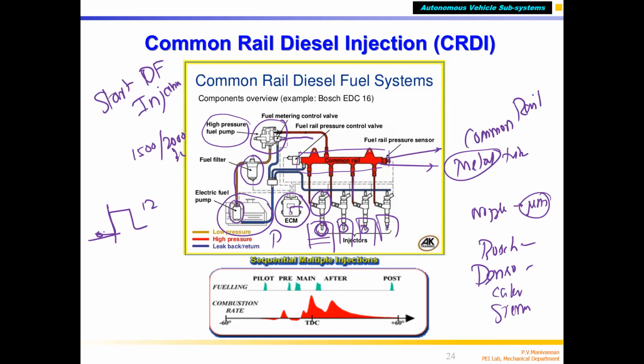Burning the diesel fuel with air takes a finite time. It is called the combustion duration, or combustion time. The combustion duration of diesel fuel depends upon the fuel, the compression ratio, all these things. But again, it is fixed. It can be 1 millisecond, 1.5 milliseconds, just like petrol. So you have to give sufficient time so that the fuel will burn.